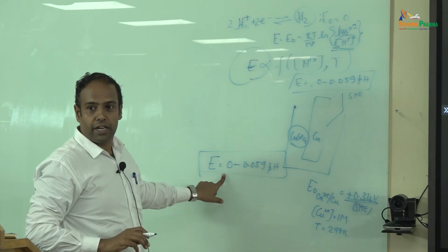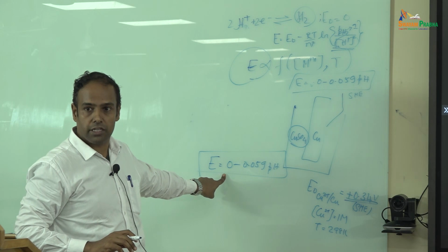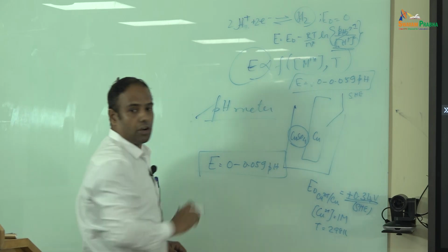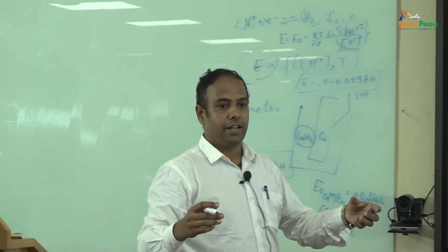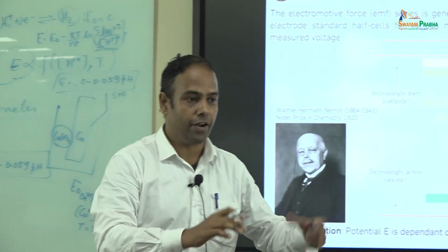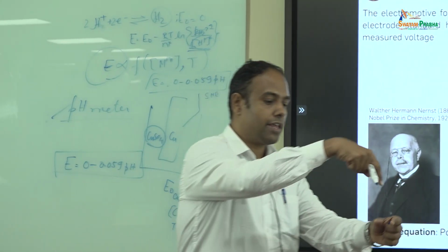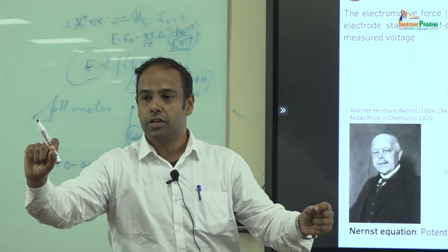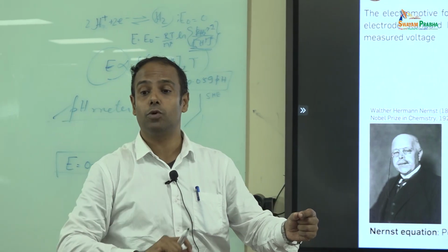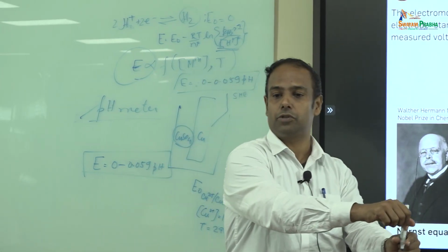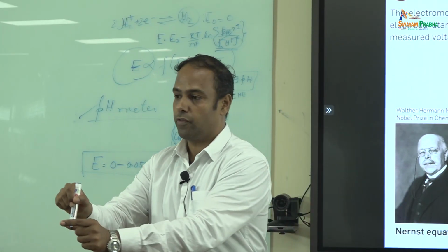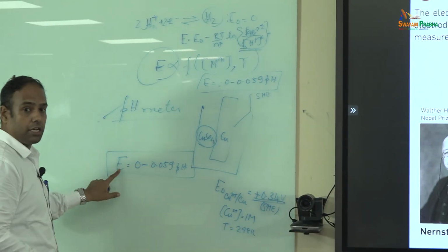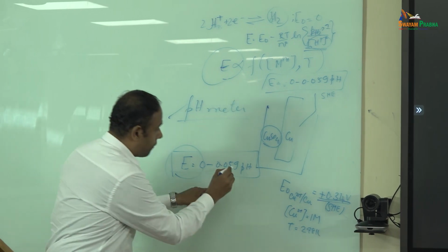Now, do you see an instrument which is using this concept? Yes, the pH meter which you use in your lab works on this concept. You take, let us say, sodium hydroxide, or you take HCl of unknown concentration, you stir it, dip the electrode and measure that potential, and that potential is what basically gives you the pH value. You say okay, sodium hydroxide should be alkaline pH, HCl or H2SO4 is acidic pH.